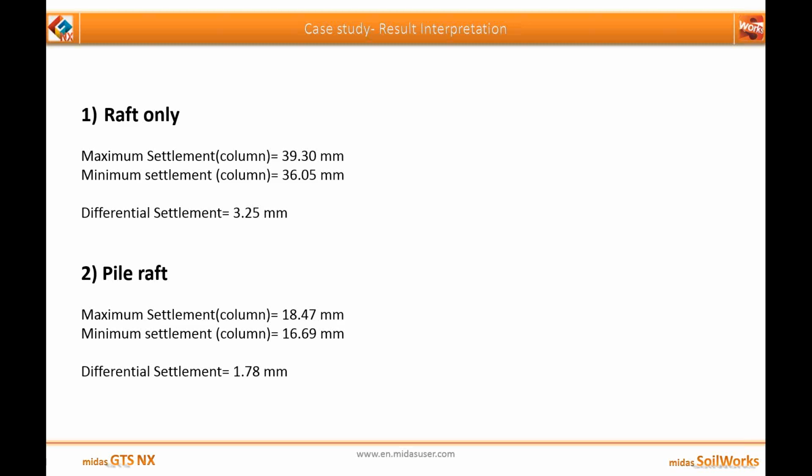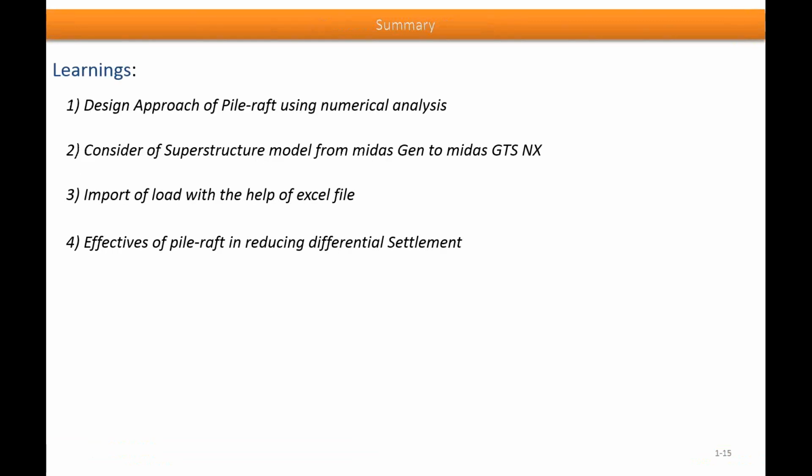Now with this, I would like to conclude today's session. So to summarize, today we learnt about the design approach of pile raft using numerical analysis, consideration of the superstructure model from MIDAS Gen to MIDAS GTS NX, import of load with the help of an Excel file, which will be very important while dealing with practical issues, and the effectiveness of pile raft in reducing the differential settlement.